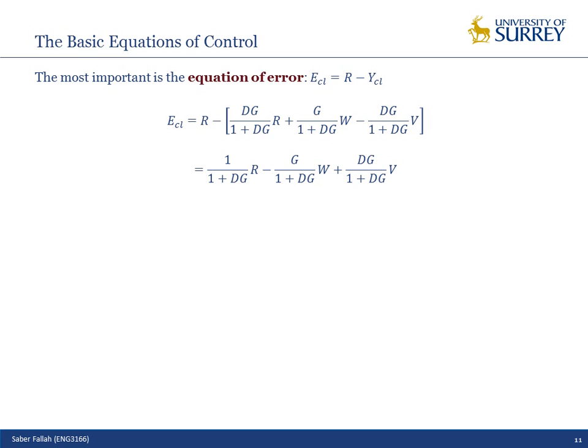I'm calculating error. So, if I want to have error between the reference and y equal to 0, this transfer function, its magnitude or its gain, should be 0. At the same time, these ratios should be 0 in order to have the perfect system, but it's not the case because there is conflict between them. How does it affect? I will show you.